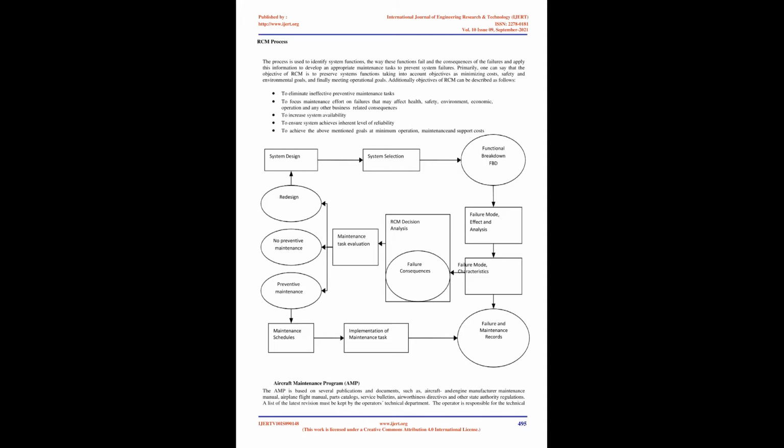Maintenance is a necessary action to sustain and restore the performance, reliability, and safety of the item. It is the combination of all technical and administrative actions, including supervision actions, intended to retain an item in, or restore it to, a state in which it can perform a required function (BS 4778, 1991). Maintainability measurements. The maintainability measure can be represented using the probability that the maintenance task will be completed